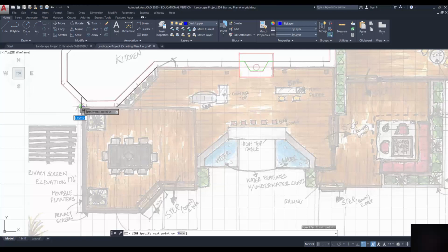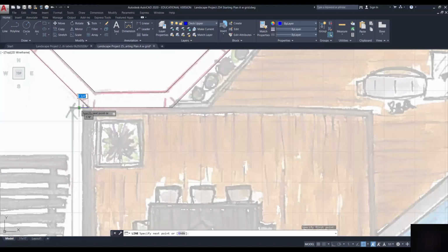There we go. Now notice how this deck moves to the left. And I've got all these snap settings and it wants to click on this. That's the grid line and so on. But what I want to do is simply move my mouse to get an estimate of the value. Now the number here is 5 1/4 inches. That's a silly number to work with. I want some really easy whole numbers. So I want 6 inches. So I'll type in here.